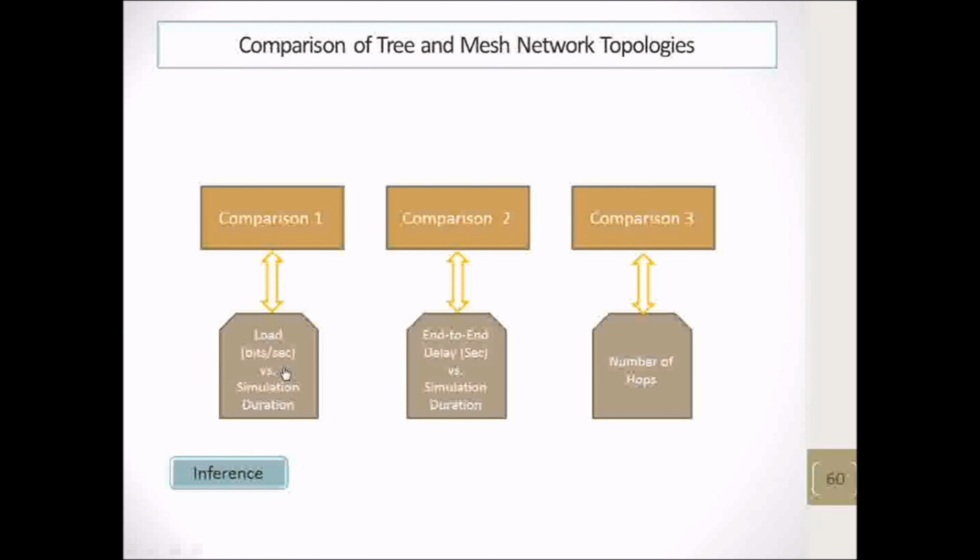Next is a VISA read block. Here it reads 4 bytes of data from the COM port. The first byte corresponds to the special character, that is asterisk, and the next 3 bytes correspond to the value fetched by the temperature sensor. And this VISA block closes a device session, and the session starts again after 100 milliseconds.